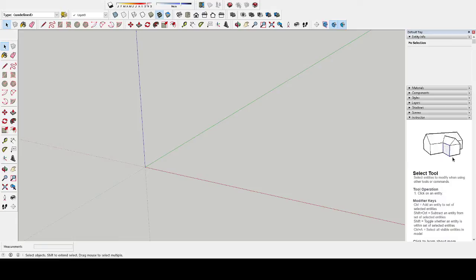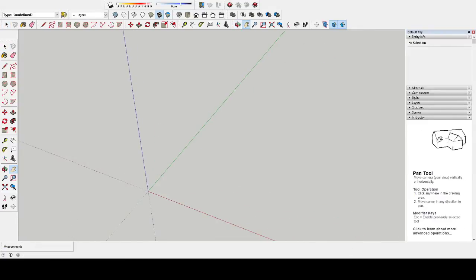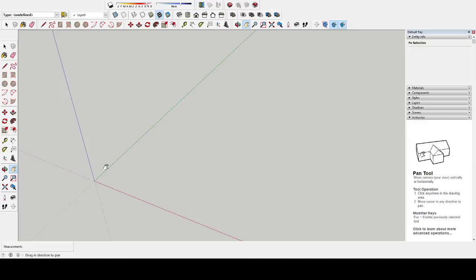Switch. Right. First step here: prevent type shift, prevent Chinese input. Otherwise, our shortcuts will fail. In this lecture, I'm going to use shortcut hotkeys instead of mouse clicks because it will speed up my design.